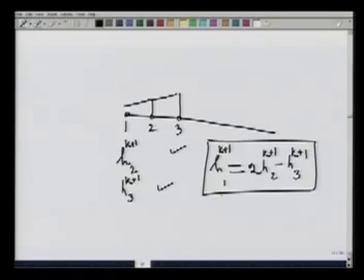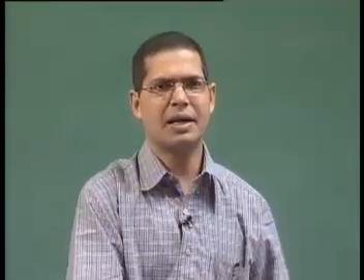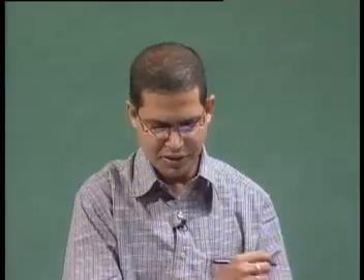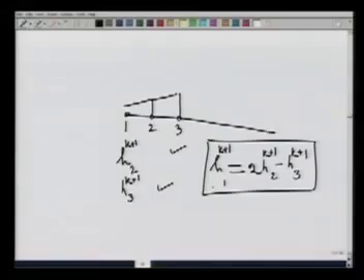So you use the extrapolation method in place of the method of characteristics, and don't forget the condition from the problem statement. For example, if you have been provided with the inflow hydrograph, then use that condition and also this condition. These two will be sufficient to find H and U at node number 1.